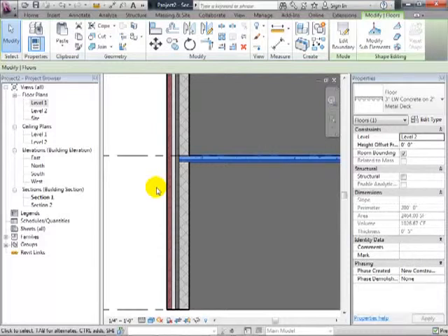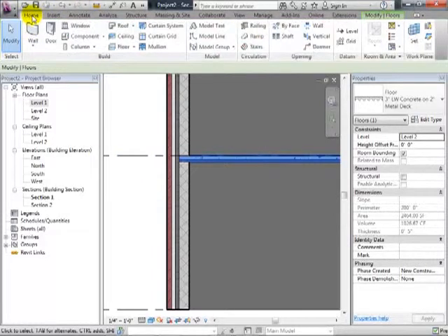The beam tools actually show up also under the Home tab. But let me give you a kind of funny thing you have to think about in terms of beams. When you're drawing beams, the hard thing to keep in mind is that they're often above your head. When we're drawing in a floor plan view, we're typically looking down at the floor, cutting at 4 feet above the floor, looking down. So when you place beams, oftentimes you'll get this funny message that says, "Oh, the elements that you just placed can't be seen in the view." And that's okay. It's just above your head.